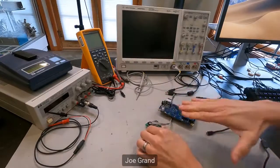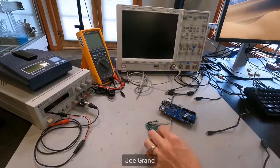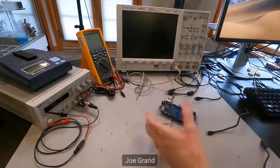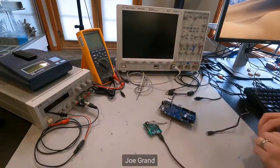And then it supports all sorts of different software tools through that FT2232 to do JTAG communication, to do logic analyzer, to do SPI and I2C and memory reading and stuff. So this is a great little device.